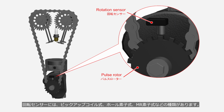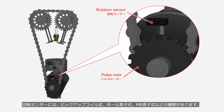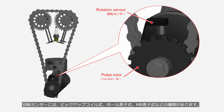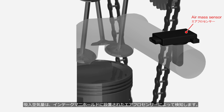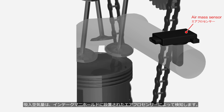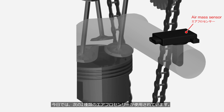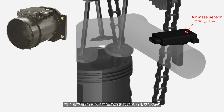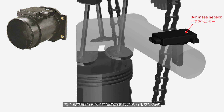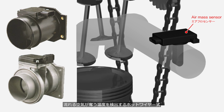There are various types of rotation sensors, such as pickup coil sensors, Hall effect sensors, and magnetoresistive sensors. The intake air amount is detected by an air mass sensor installed in the intake manifold. Today, two types of air mass sensors are used. The Kármán vortex sensor, which counts the vortices created by the flowing air, and the hot wire sensor, which detects the temperature drop caused by the flowing air.